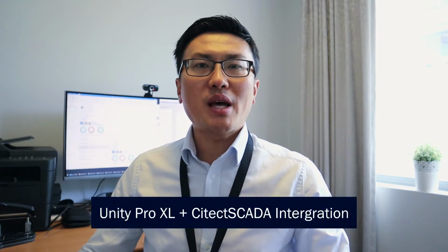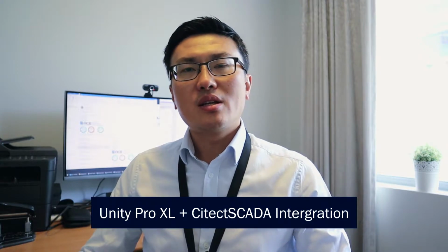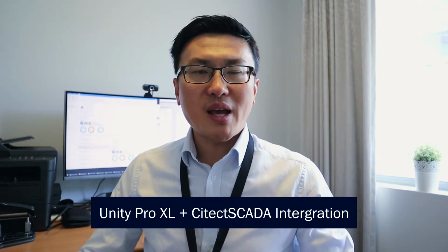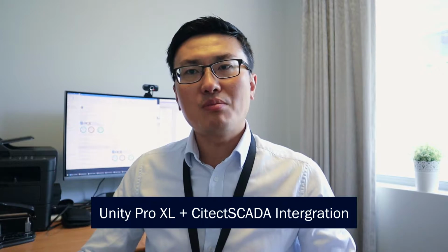Today's topic is about UnityPro integration into the CitectSCADA. UnityPro is the PLC software language that we use to program Schneider PLCs. And CitectSCADA is the SCADA platform, and it's a server-based SCADA platform that we will install on a computer or an industrial computer to run the software to interrogate the I/O points from the PLC or RTU or any other intelligent devices in the field.